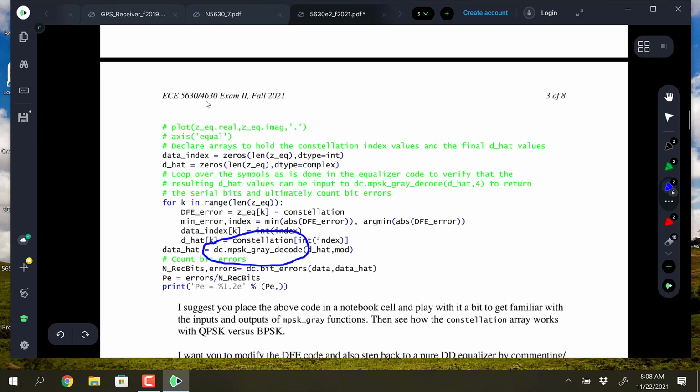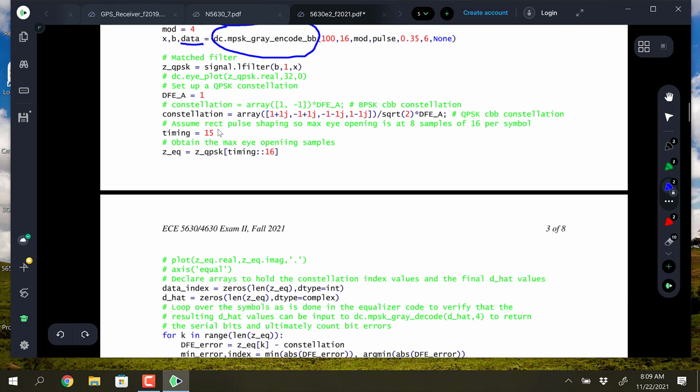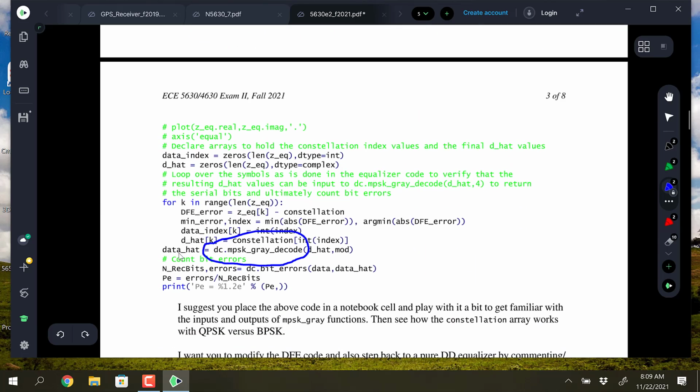And then when you go ahead and decode over here, you give it a complex baseband set of samples that would be the I and Q values from the optimum sampling instant. And what it will then return is a bit stream that will correspond to the detection level. And now, because of filtering that still is going on, processing the channel filter, match filter, and so on, the bits that come out of here, data hat, are not time aligned with the ones that went in. They're going to be shifted to the right slightly because of the propagation and going through the filters. But the bit errors function there takes data and data hat, and it's synchronized.